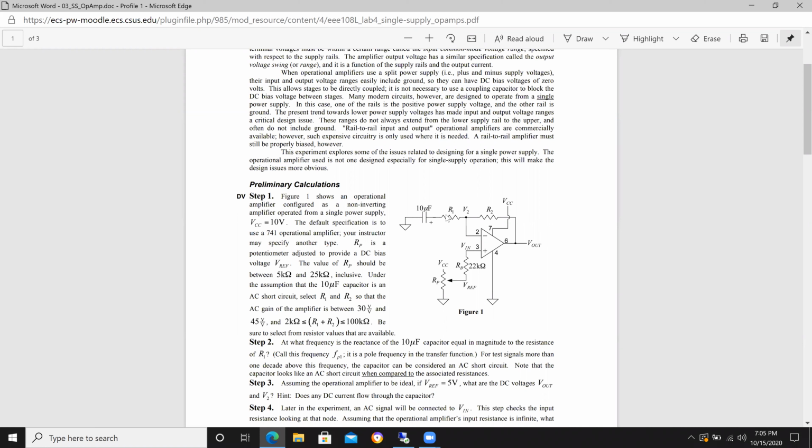for DC. What happens when you get rid of this capacitor and short circuit this right here? What happens to your DC gain? Hopefully it just kind of clicked for you that, okay, now my DC gain is the same, right? Because there's a DC path. Now my DC gain is, say, 45, just like my AC gain. Okay, what does that do to your circuit?